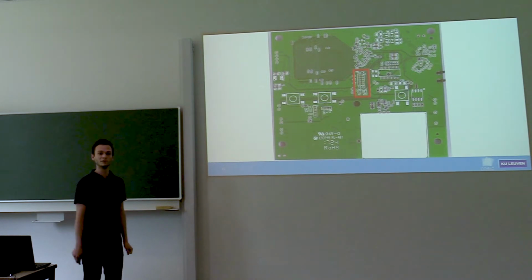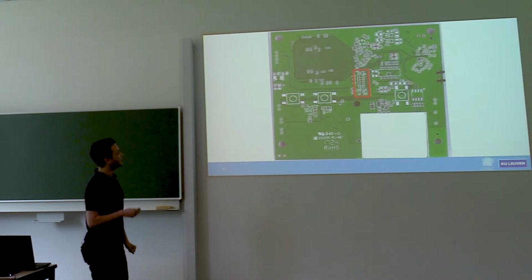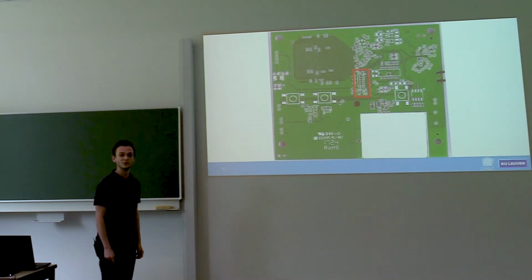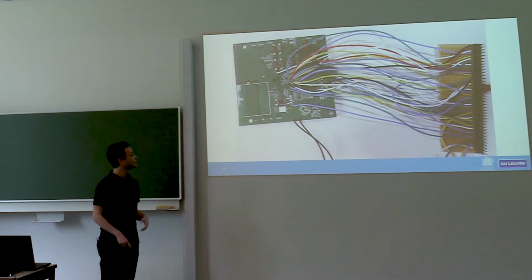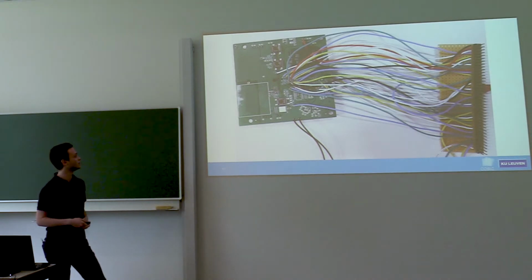This is the backside of the vacuum cleaner board, and you can see a lot of test points all over, but in the middle it's also marked, and it's marked using RX and TX, so receive and transmit. This is the UART interface of this particular vacuum robot. So this is what you do. You solder wires to all of the test points you think might be interesting. You can then hook up a logic analyzer to see what is going on.